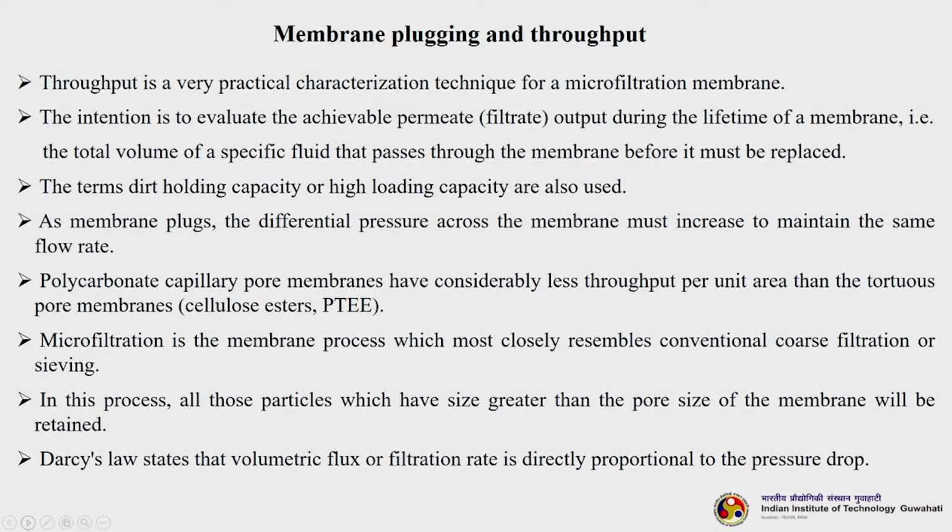As the membrane plugs, the differential pressure across the membrane must increase to maintain the same flow rate. Once you pressurize the system and the process is on, permeate will start coming. Initially we will get more permeate because the membrane is clean. Slowly solutes will deposit on the surface of the membrane, concentration polarization will build up and cake may build up.